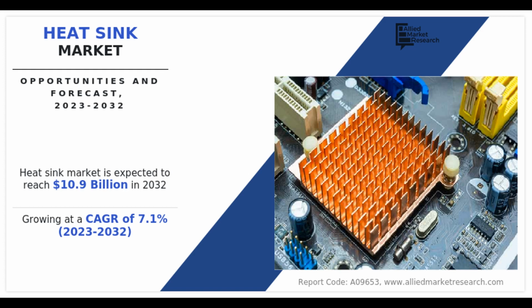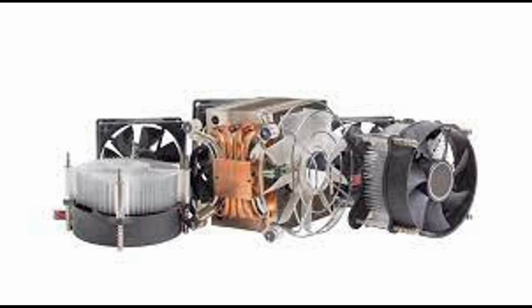The increased surface area provided by the pins allows for more efficient heat transfer, enabling the heatsink to effectively cool the electronic device or system. Pin-fin heatsinks offer several advantages. High surface area density. The densely packed arrangement of cylindrical pins maximizes the surface area available for heat transfer, resulting in efficient cooling performance. Compact design.